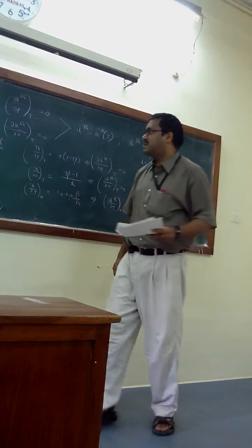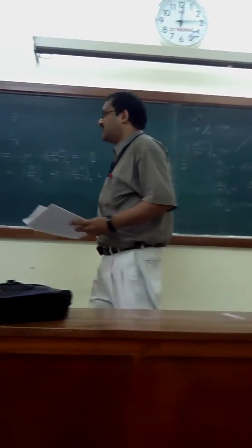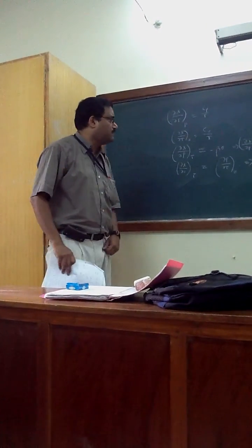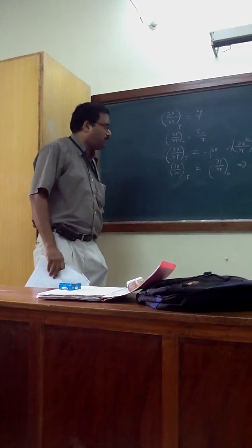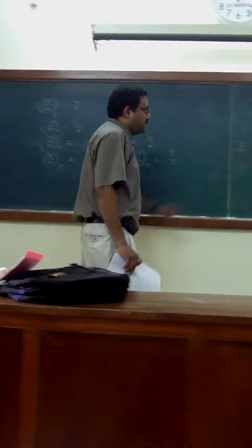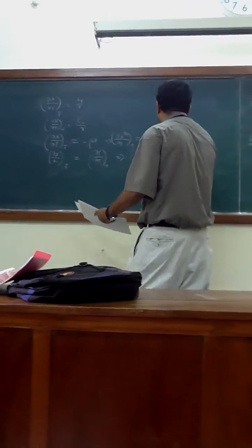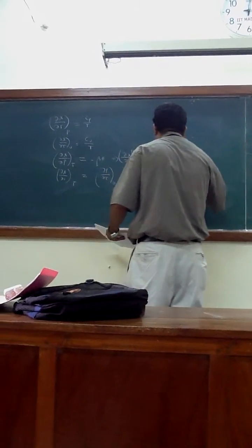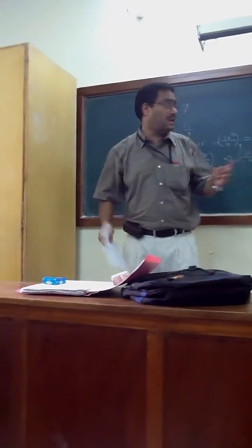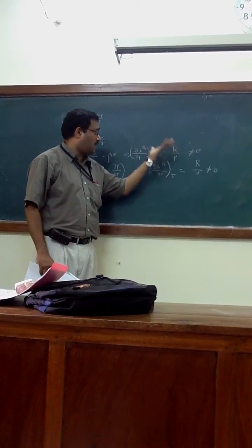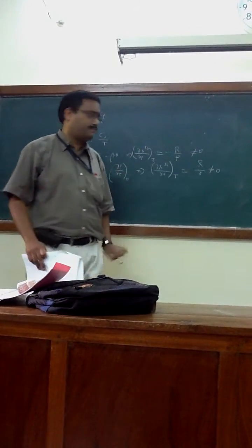Okay. So now this actual situation is different here for S ideal gas, and it says that S ig is definitely a function of temperature and pressure, the TP plane, or temperature and volume. It is not like these functions, because these terms are not becoming zero. This is non-zero, this is non-zero. In fact, at pressure tending to zero, this term will be a large number, so it contributes quite a lot.